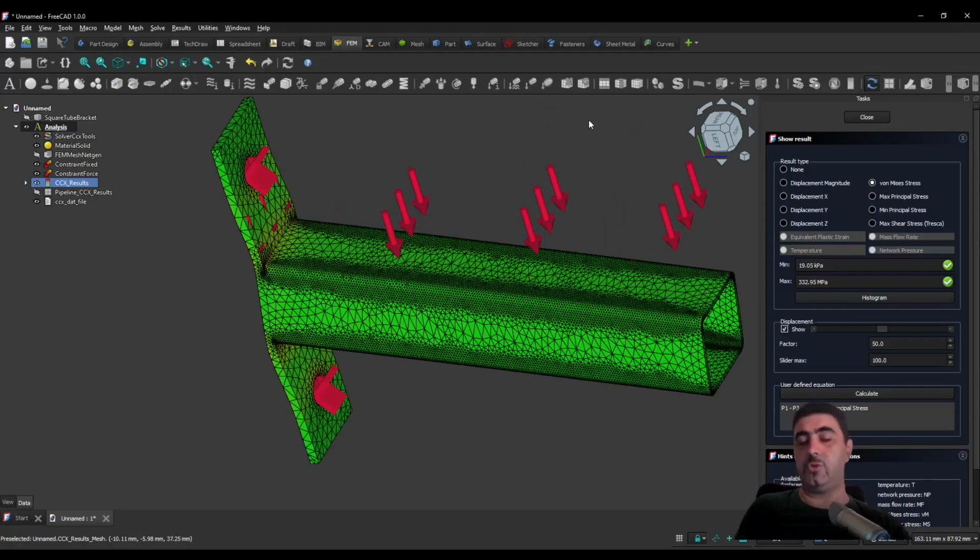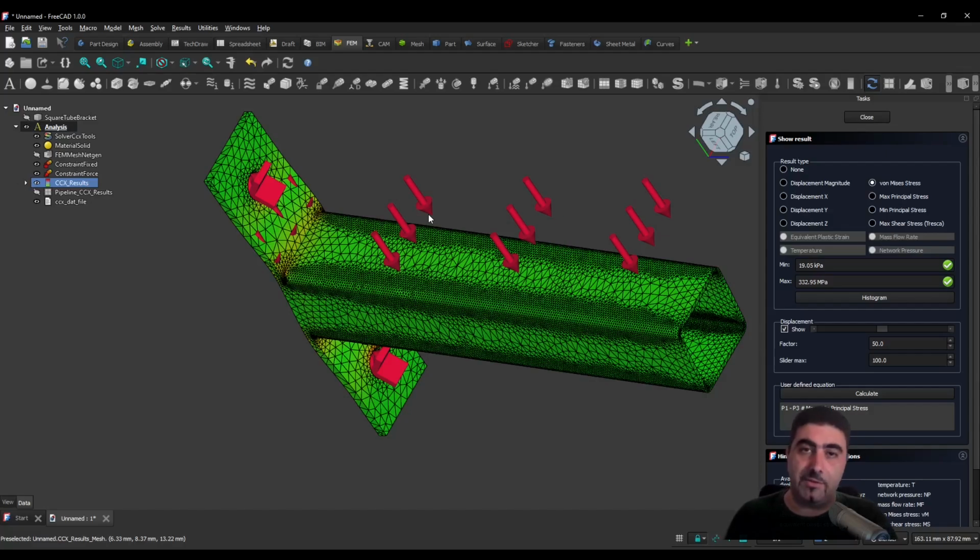This is very well shown by our analysis, but there's another problem, right? When you have very fine meshes in finite element analysis, near these sharp edges, especially if you've got torsional loads going through them, you get singularities, right? You get stuff being divided by other stuff that tends towards zero, and you get numbers that are not real. So if this was a job that I took, right, what would I say? Can this 20 by 20 by 1 millimeter thick tube handle 20 kilograms?